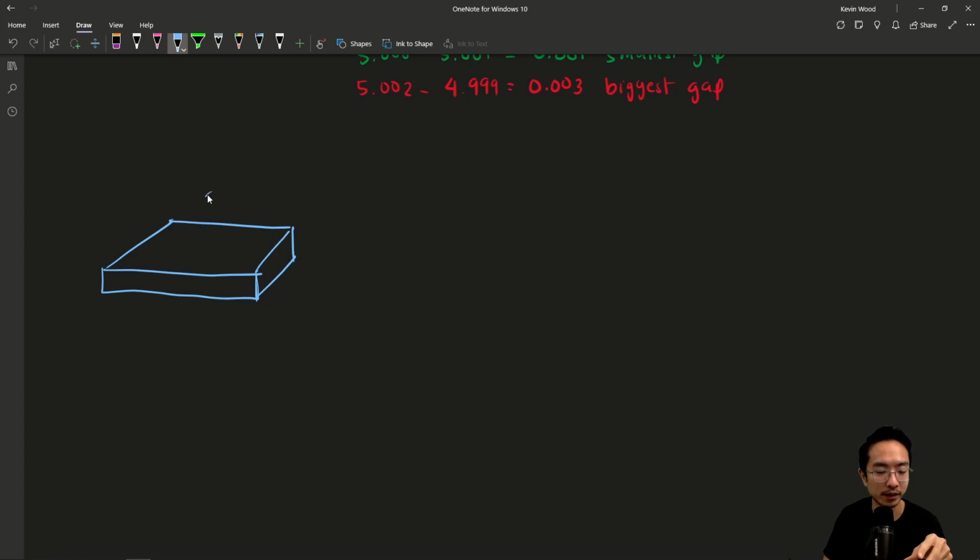So this is our plate, and then maybe now we want to press fit a dowel inside. So again, maybe this dowel is gonna be like 5, plus 0, and then minus 0.001. Maybe you could also find a dowel that's slightly oversized. I think they might sell that too, but let's just use the same dowel for the sake of this example, to be similar with the dowel, but we'll dimension the hole differently.